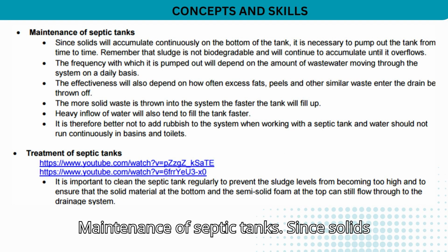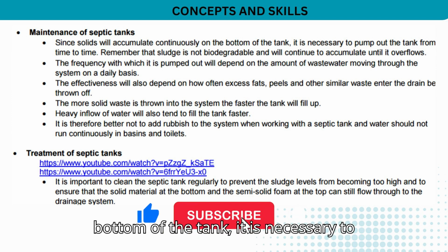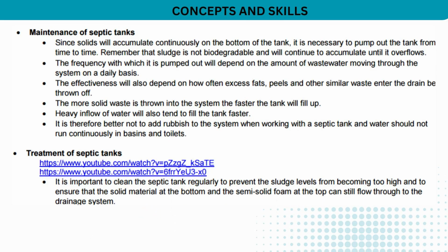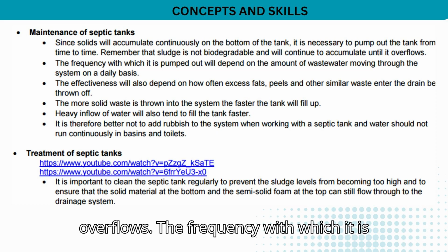Maintenance of septic tanks. Since solids will accumulate continuously on the bottom of the tank, it is necessary to pump out the tank from time to time. Remember that sludge is not biodegradable and will continue to accumulate until it overflows.